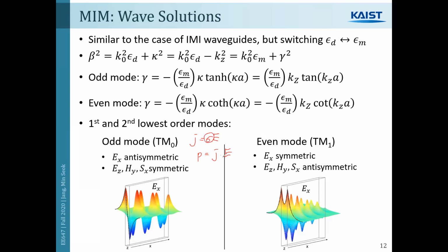So if the real part of the conductivity is large, you have power dissipation due to heat generation. In metals, the conductivity tends to be large, and its real part is also large. Because of that, metals tend to create a large current if you have an electromagnetic wave inside, and that is energy loss. But in a dielectric, the real part of the conductivity is nearly zero, because there are no free electrons, or at least very, very few free electrons. Because of that, energy dissipation is nearly zero, and that's the reason why a dielectric waveguide doesn't have that much loss. So that's basically the main reason.